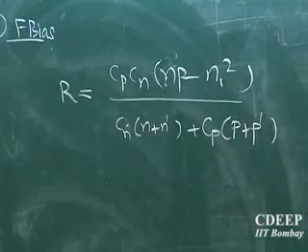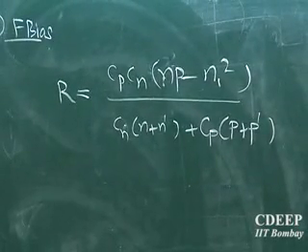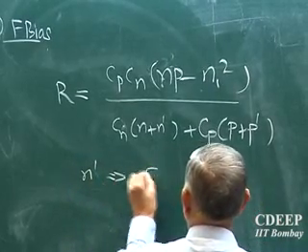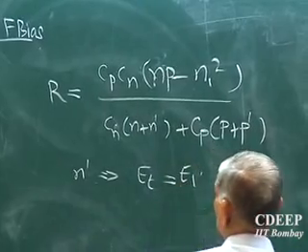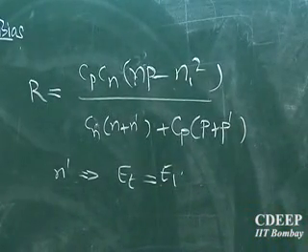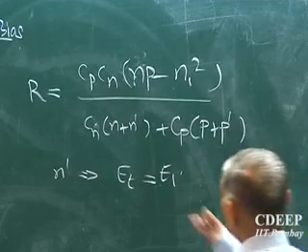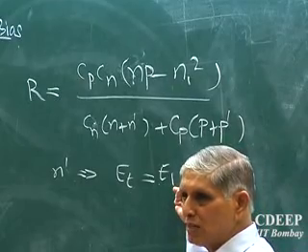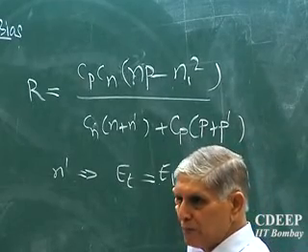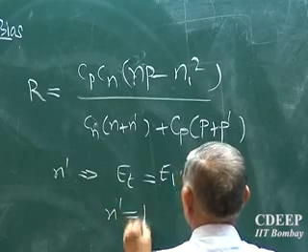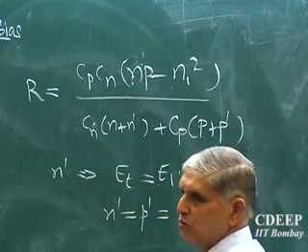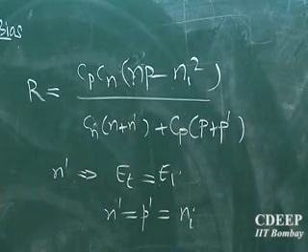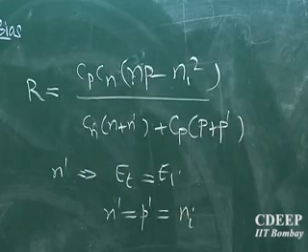So in case this is true, we can assume right now that n dash is related to the trap level at Eg by 2, that is, at the mid gap. At the mid gap, if the trap level is at the mid gap, what is the concentration when the Fermi level is at half of the band gap? So n dash must be equal to p dash, which must be equal to ni. Is that clear? If they are halfway, they must be equal to the intrinsic value.